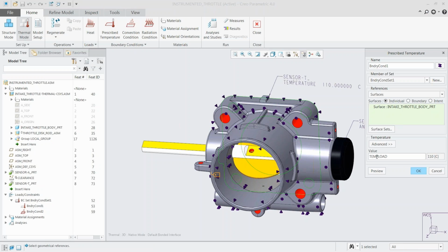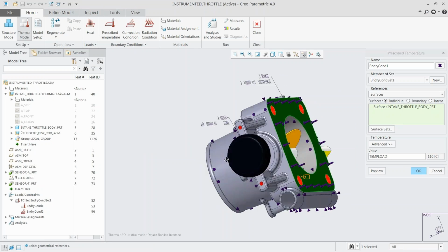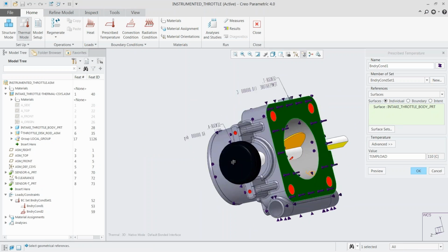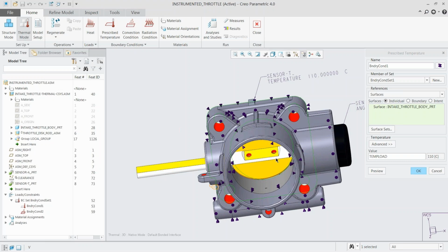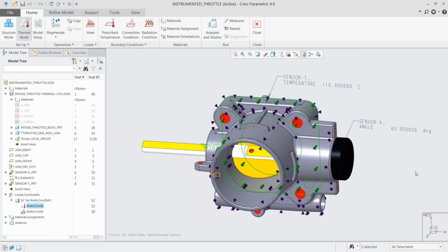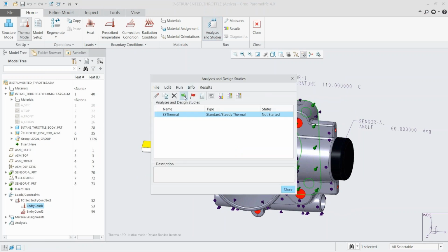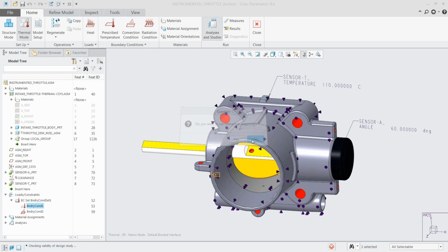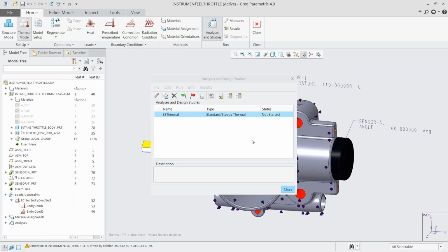And so the value we want is our temp load, which has all of that temperature information that we brought down from ThingWorx. That load's going to be on the back wall there, and it's associated to our temperature sensor. Once we have that loaded, we can simply run our diagnostic simulation here, and it'll go through the information for us. It should be pretty quick, only take a few seconds, and we've got our results.